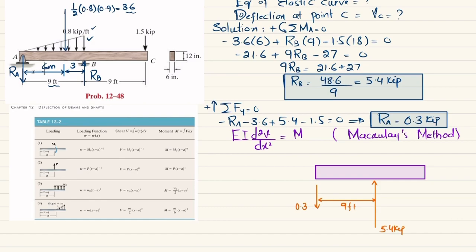Okay, so what we will do is that we will add this load from first point till the last end. This was the load till this, and that is 0.8 kips per feet, that is triangular load downward, and you can see this is over length of 9 feet. So this is again 9 feet, so this load will be double, so it will be 1.6 kips per feet, and that will be downward.